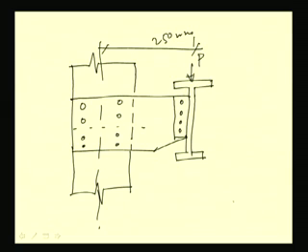Now, with this configuration we have to find out the permissible value of P. That means, here 4 rivets in each row have been provided to connect this joint, and with this plate 4 rivets have been made to connect this gantry girder, and the gantry girder is connected in this way. So, 3 rivets, right, and this eccentricity here is 50 mm.